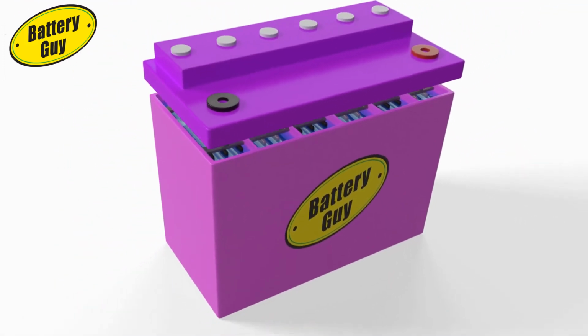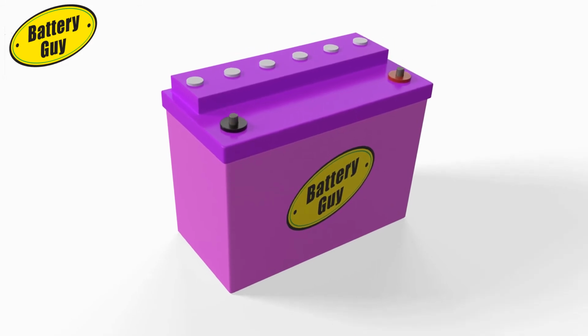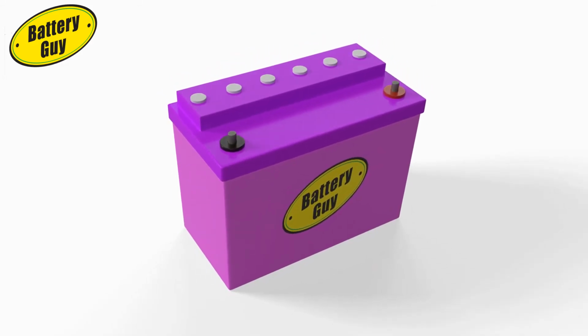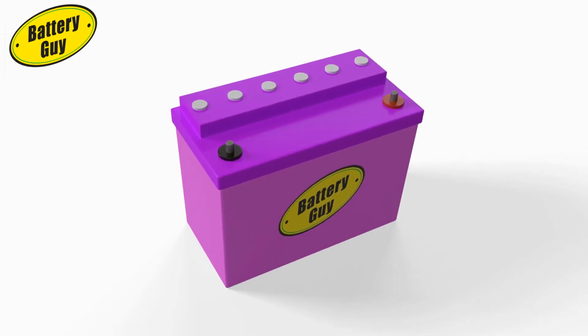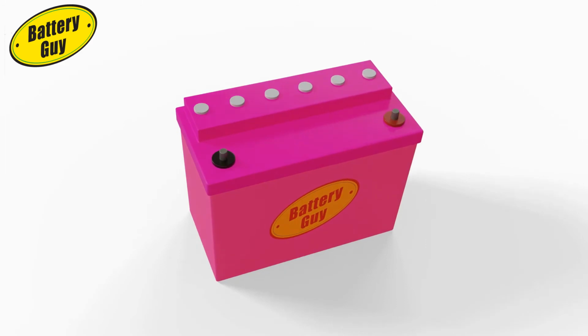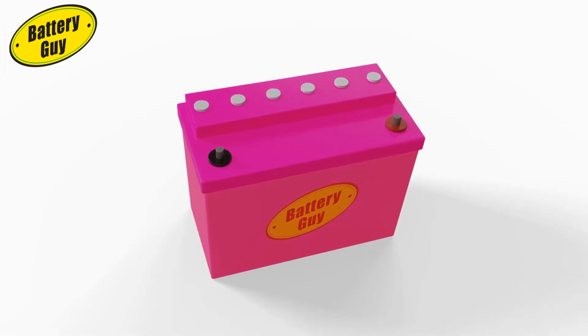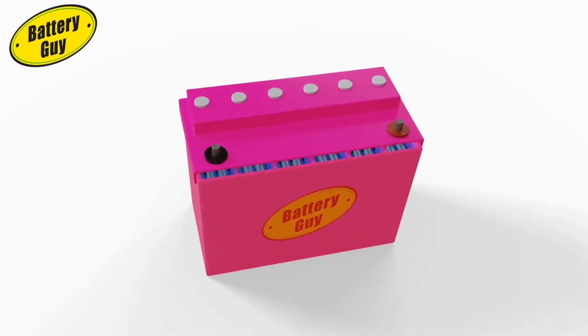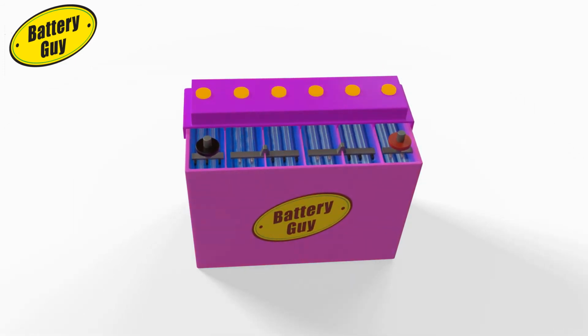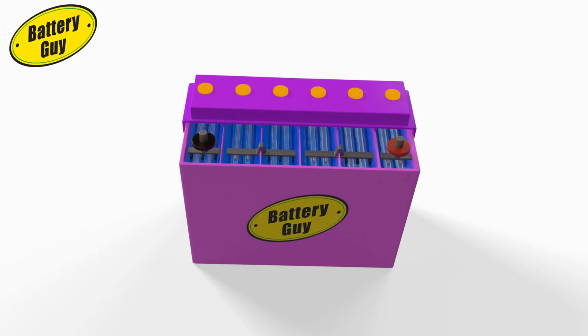If a cell develops a fault or the battery is abused, charged or discharged too quickly, the internal components will overheat, causing gases to build up inside the case. In extreme situations, these can cause a fire or an explosion. To avoid this, the lid contains vents, one for each cell, that allow these gases to escape.